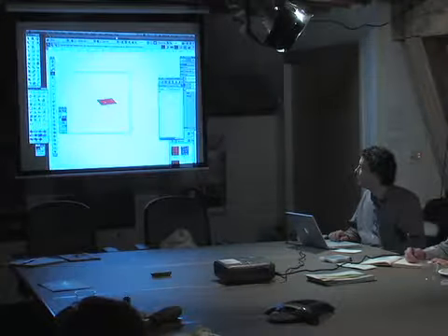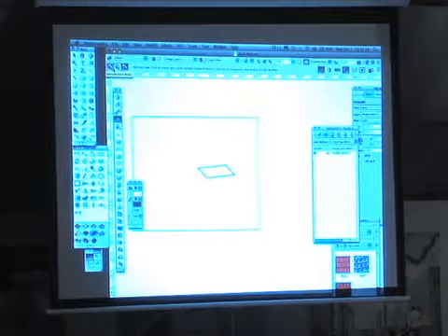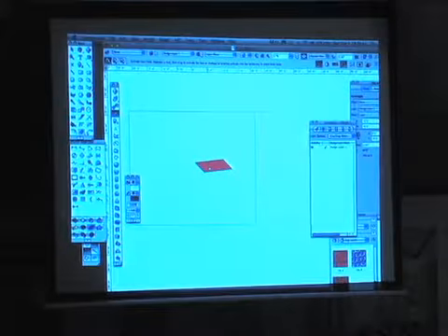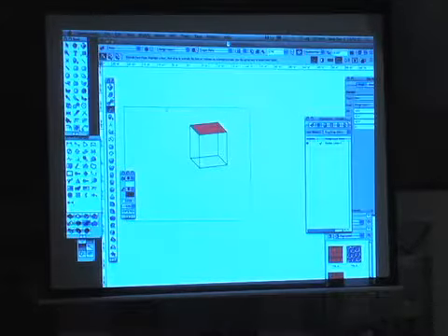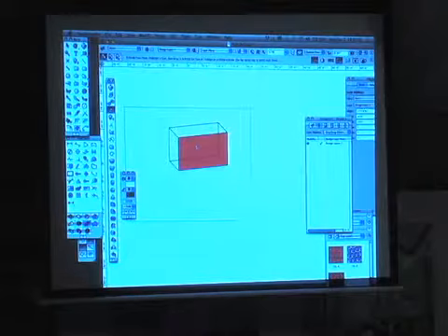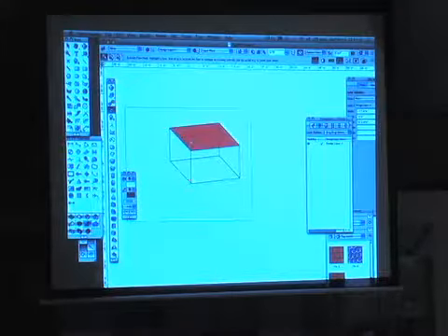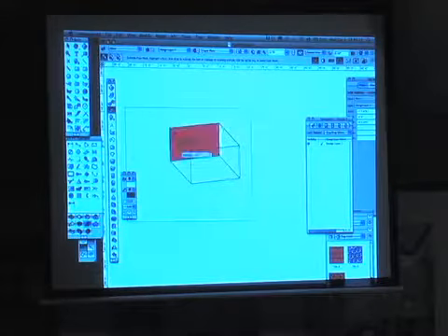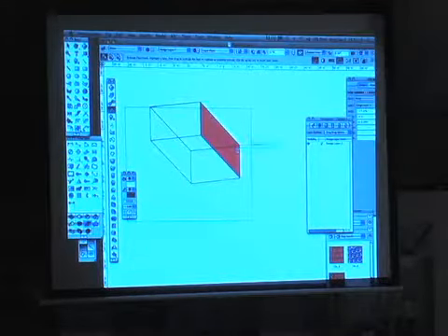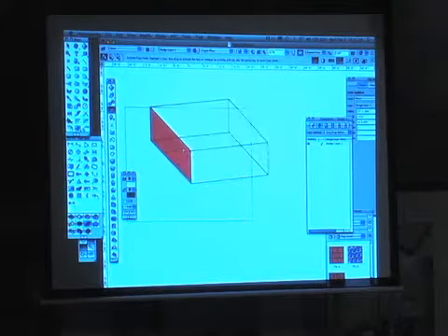So for the face, we've got three modes. We've got the extrude face, the move face, and a subface mode which allows us to subtract something from this. With the first mode, the extrude face, we hover over the face we want to adjust, and boom, we can pull that up. Click on this face, pull that out. If you hold down the command key or the alt option key, I can select this face in the back and pull it. Or if you hold down the alt key, I can get to faces that I can't see. So I'm able to push and pull my model around.